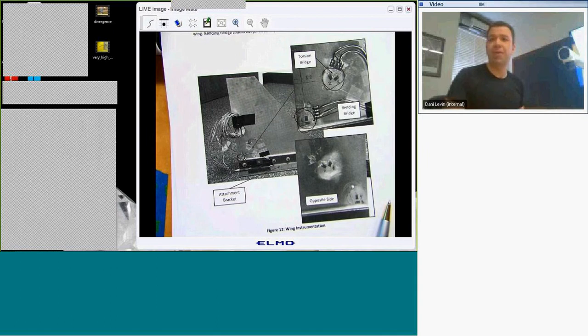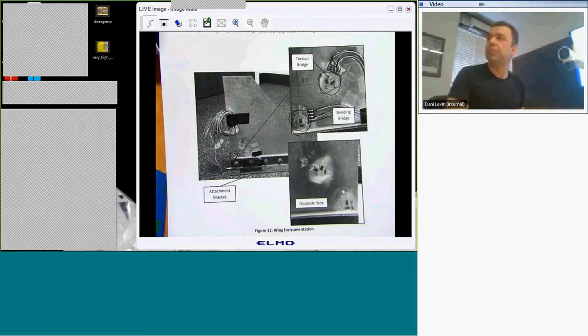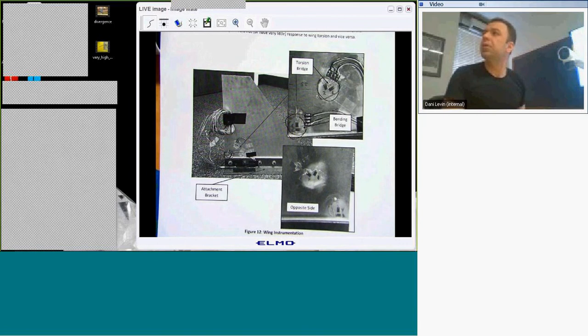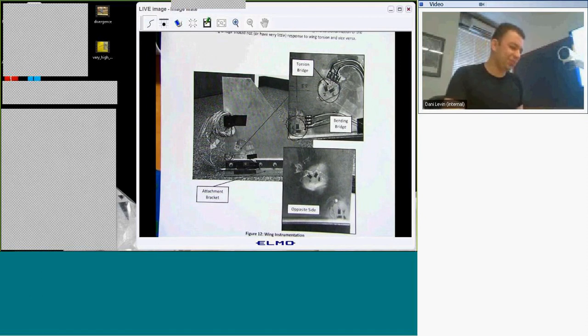But this principle is very useful for us to make a custom load cell. This is a custom load cell. I'm just using this principle to instrument what I want. Basically, this is the full bridge model. You could have gone for the half bridge model also, where you would be using only one strain gauge. Yes.